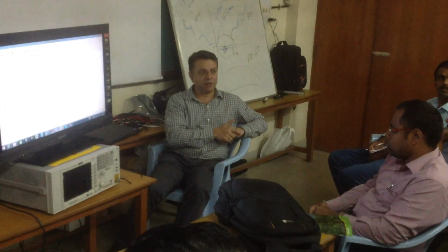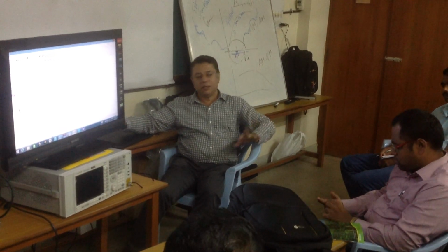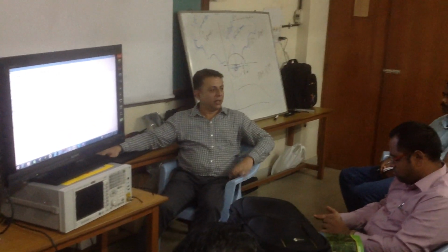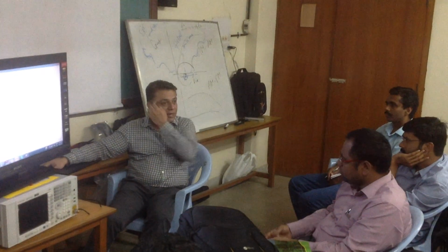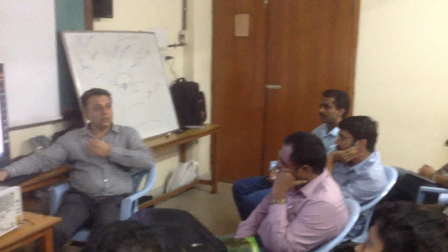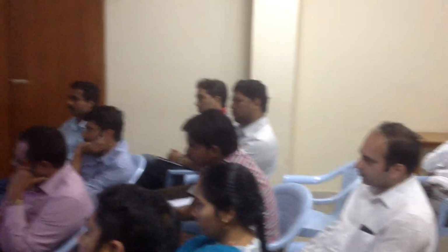In power amplifiers, see, this is very important. You know, instability in LNAs, everybody has seen it, they can handle it. But instability in PAs, probably people are not aware because they are used to handling PAs which are stable. Their only worry is about power. But GaN is not like that. There is an additional problem with that, which is the stability problem. Okay, I'll come to that also, in the next example when I take it.